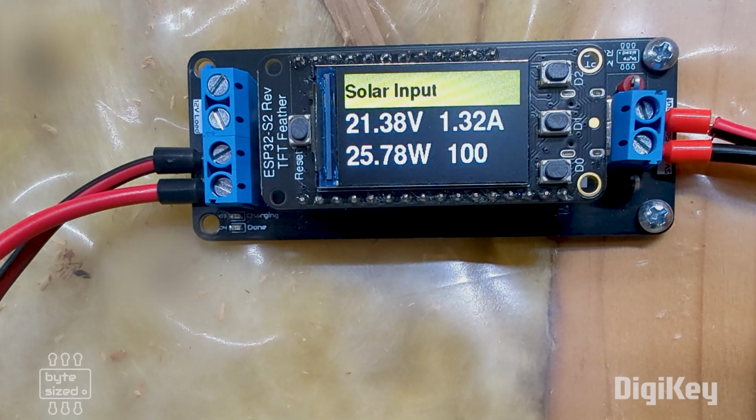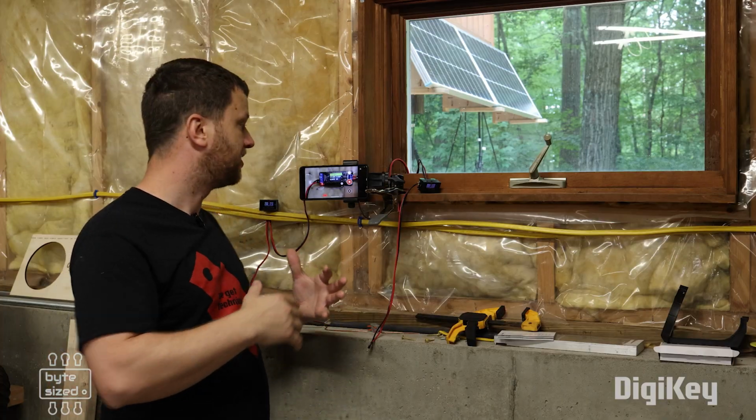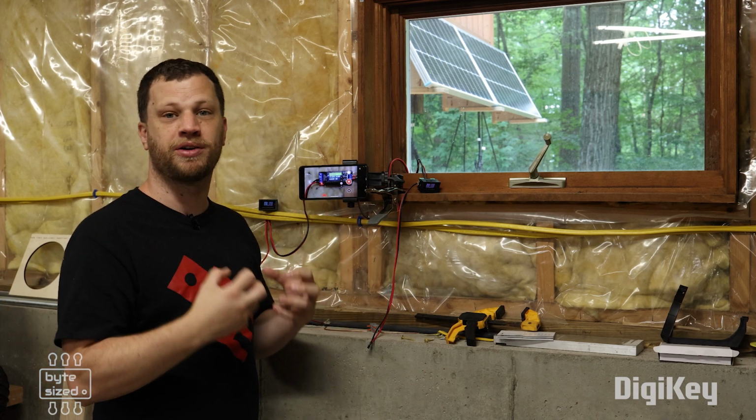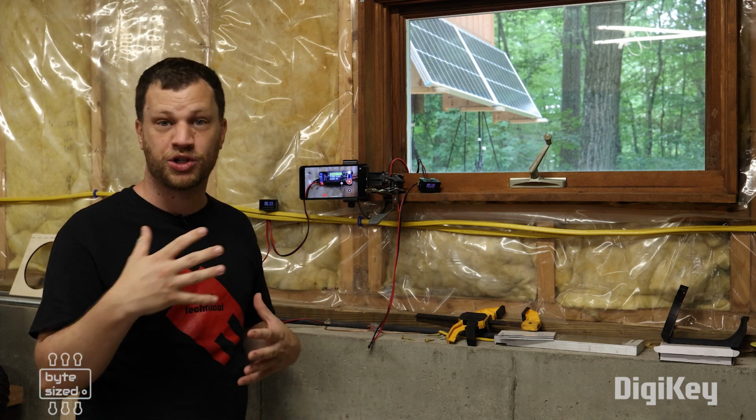I want you to keep an eye on that fourth value. That's the digital potentiometer. I'm watching that potentiometer value change as the power increases, and then it'll overshoot, and then the power will go back down, so then it backtracks and tries to correct itself. This really illustrates why you need an MPPT charge controller on a solar panel, because for about 30 seconds that sun came out, and the MPPT charge controller jumped all over it, and it started sucking out more power from that panel, whereas a traditional charge controller would not have been able to adjust like that.